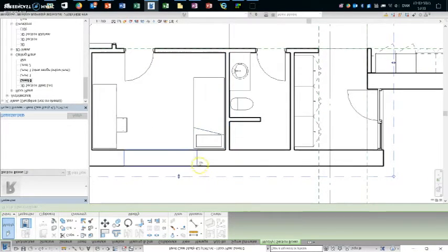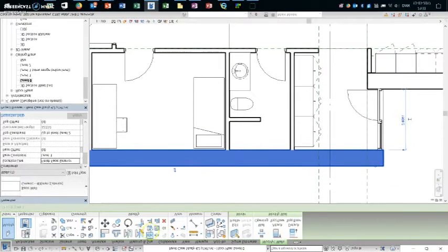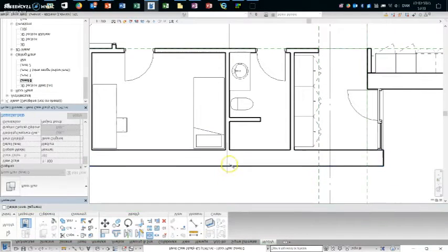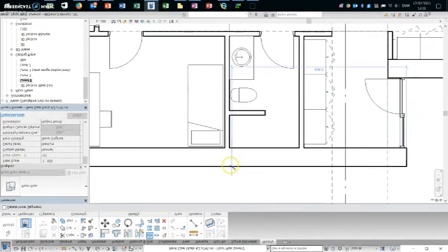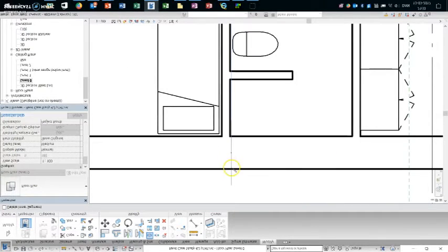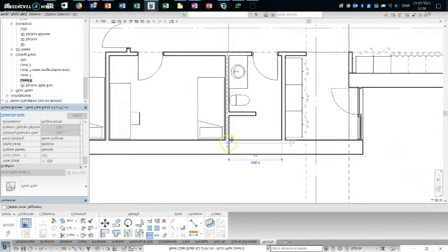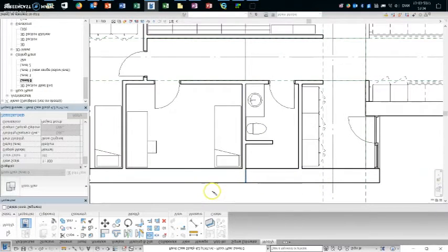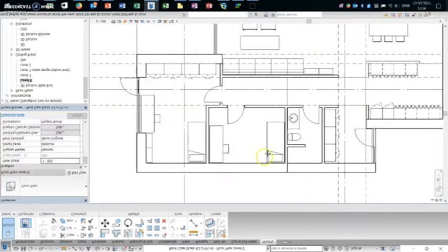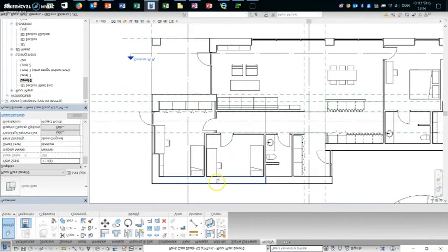So if we click the wall, we can choose the split tool, and we pick a spot. We have to zoom in where it's aligned like this with the underlying wall to the toilet. Click split, and we should have created 2 elements right now. Press escape a couple of times.